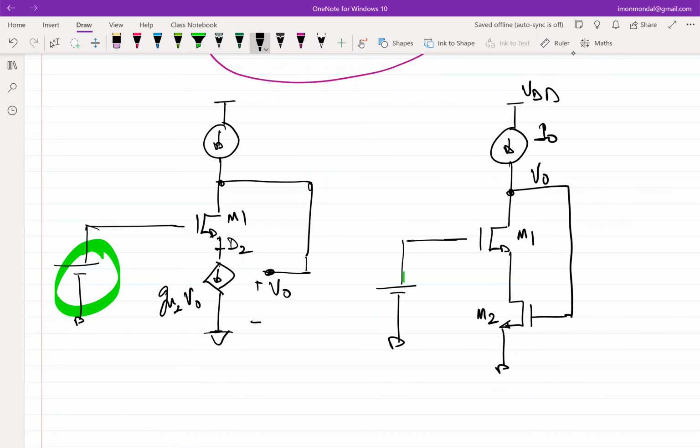When I say it will work or not, what I mean is whether at least it will be biased properly or not, right? Or whether we'll have to apply a bias. What are we arguing with ourselves? We are arguing whether the transistor will be in saturation, at least. Everything we have been doing assumes that when we say my VCCS is of this model, we are inherently assuming that the transistor has to be in saturation. Otherwise, this model is not valid.